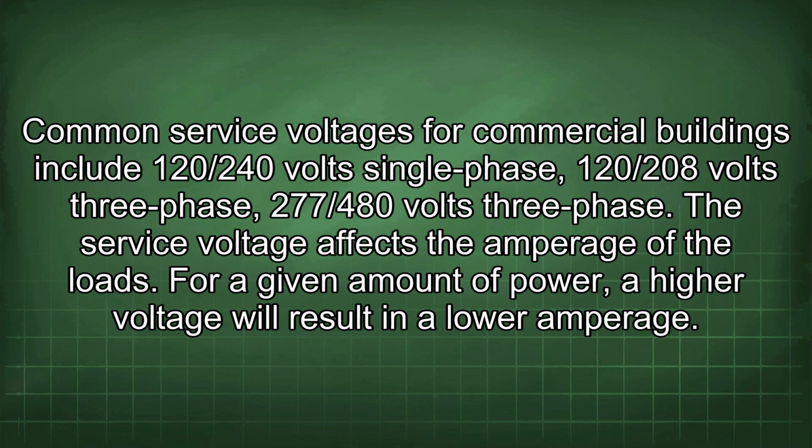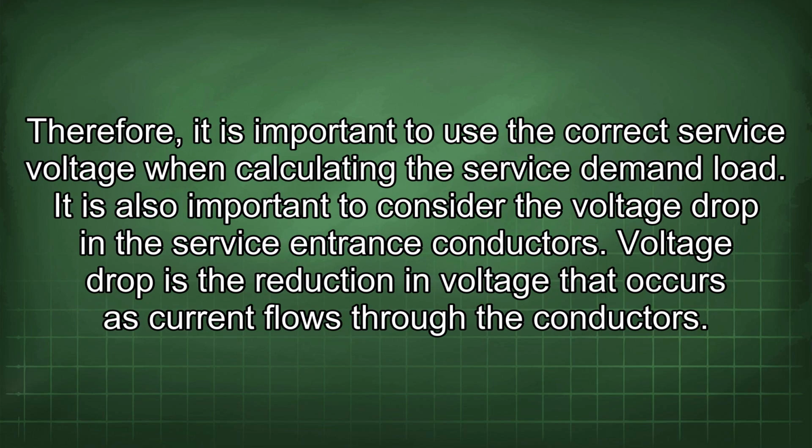Common service voltages for commercial buildings include 120/240 volt single phase, 120/208 volts 3 phase, 277/480 volts 3 phase. The service voltage affects the amperage of the loads. For a given amount of power, a higher voltage will result in a lower amperage. Therefore, it is important to use the correct service voltage when calculating the service demand load.